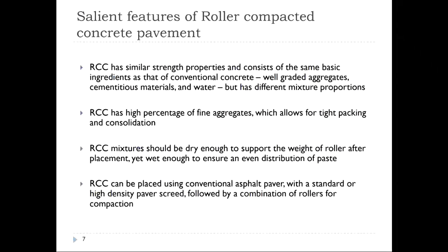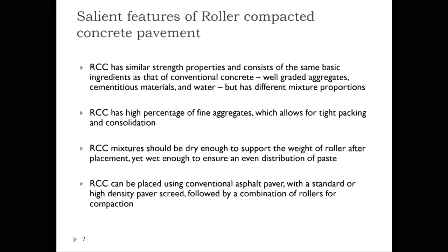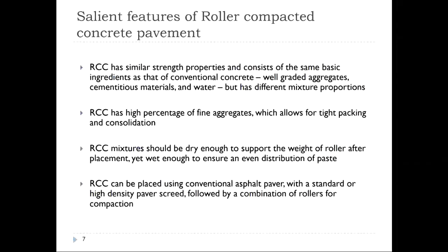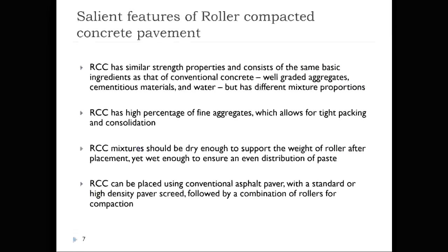So they should be dry enough to support the weight of rollers after placement, yet wet enough to ensure an even distribution of paste. Okay. Now, roller compacted concrete pavements can be placed using a conventional asphalt paver with a standard or a high density paver screed, followed by a combination of rollers for compaction.